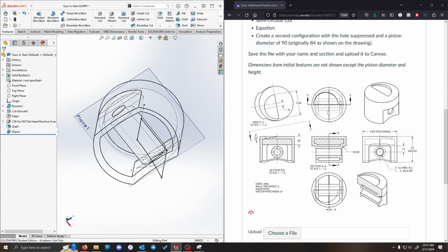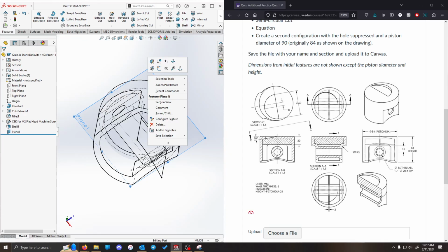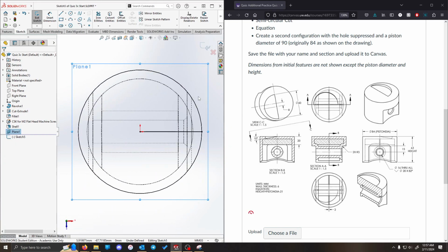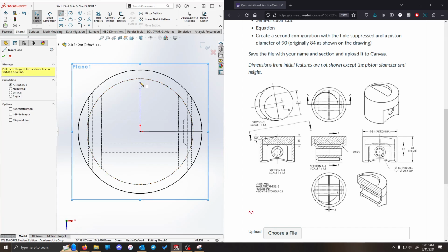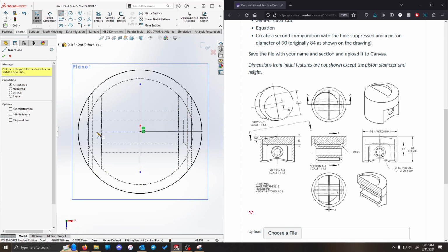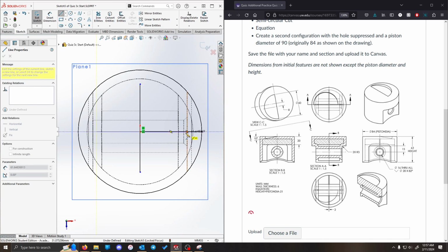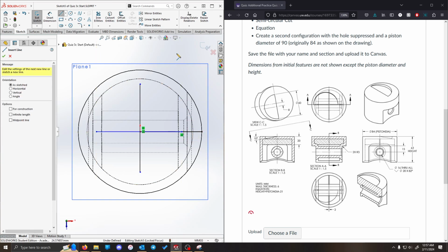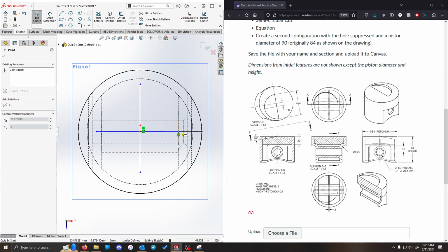Now we can just draw in our rib sketch. So this one's just going to be a nice simple plus on that surface. Looks like it goes right through the middle. And fortunately for us, when we open our sketch, Control 8, we can see that our origin is already there for us. So I'm just going to draw in our plus. You can double click to stop a line while you're drawing it if you would like. Saves a little bit of time. And let's see, you can see that we've got a point. It's getting a little messy because we have that other sketch in the way.